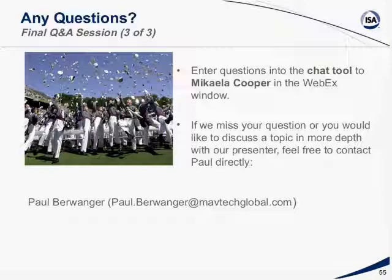That would depend on the priority. Let's just use the high alarm. You alarm on the high. If the priority is already your highest priority, you do not have a higher priority than that, then you don't need another alarm. If the high alarm is, say, for example, a medium priority, then you could configure an alarm of higher priority to that. Obviously, less operator time to respond. But really, you have to take a look at realistically, what is the operator time to respond? You've got the high alarm for the operator to respond, and then you've got high-high that shuts you down.